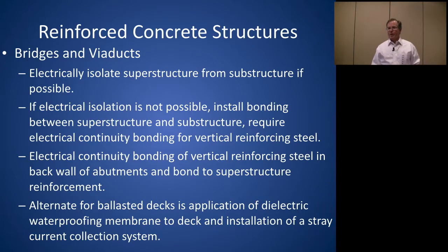Well, you've got to have an inspector out there watching it too. You know, and a lot of times they'll put protection board on top of it. Even though the manufacturer says you don't need protection board, they'll put the asphalt protection board on there. It's basically asphalted quarter-inch plywood to help protect it. Inspection's a big deal on all this stuff.